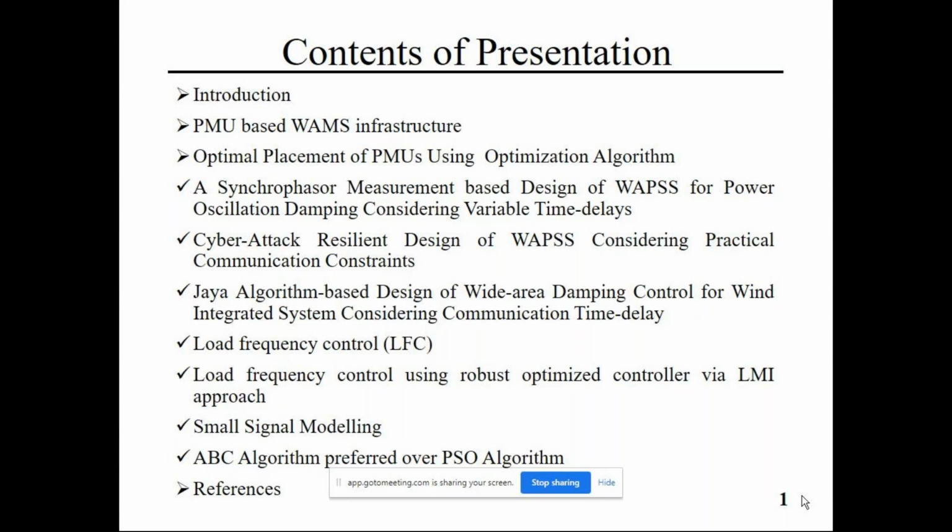So when you go for reduced order modeling without sacrificing the original behavior of the system, you have to discriminate between the slow states and the fast states, and accordingly the optimization function has to be formulated so that you are preserving the original